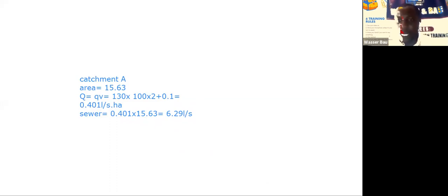Using the calculator, 1/200 means 1 divided by 200, so the slope is 0.005. From what we said yesterday, somebody will give you this as a slope, or give it to you in percentage. If I give you the same slope in percentage, I simply multiply by 100.